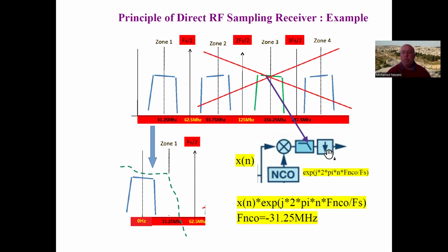If you decimate by 2, half of the samples are gone, and you improve by 3 dB. If you decimate by 4, you improve the SNR by 6 dB. And the SNR we're talking about here is always within the SNR of the ADC, which is from full scale down to the quantization noise, and we're going to show in the next session how you analyze all of that.